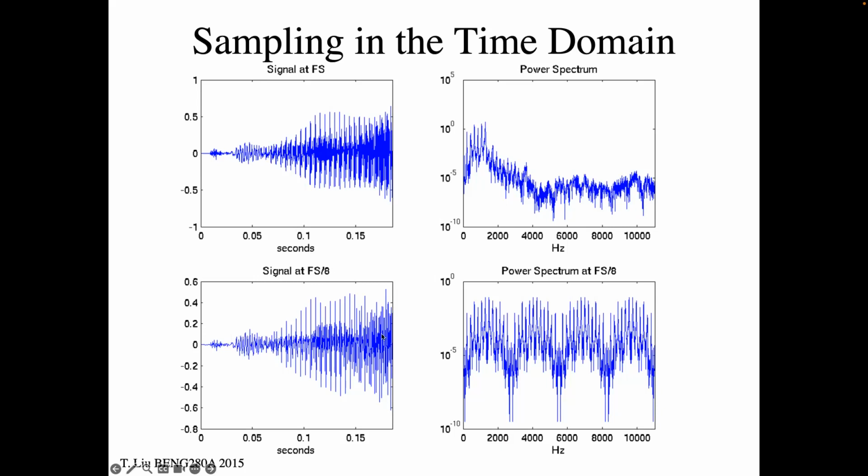The signal looks like this when you plot it in MATLAB. Take the Fourier transform of this signal, and you get this on the right here. That looks totally different than this, right? And it has some interesting features, in that it looks like it's the same function replicated over and over again. This thing gets replicated here, which gets replicated here, which gets replicated here. So by undersampling our continuous signal, we've turned it into a periodic function, right? Which is kind of an interesting artifact.